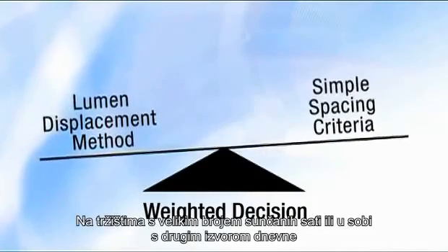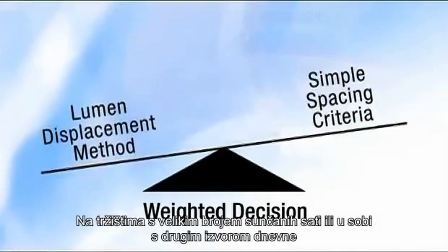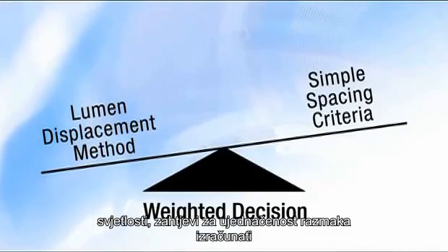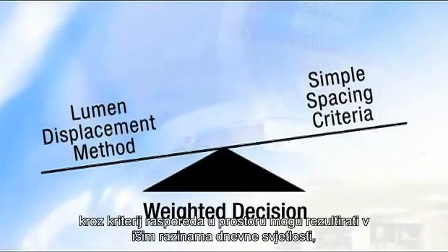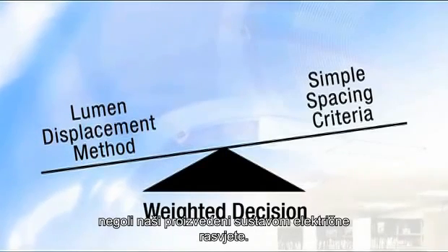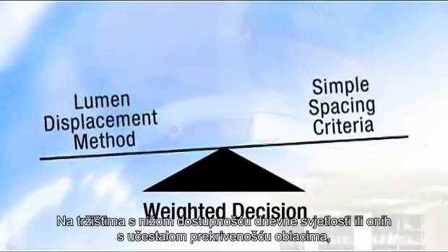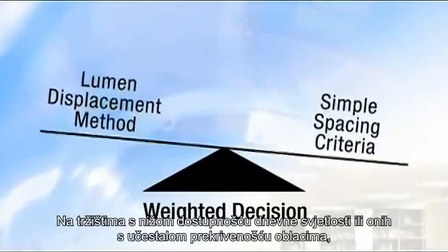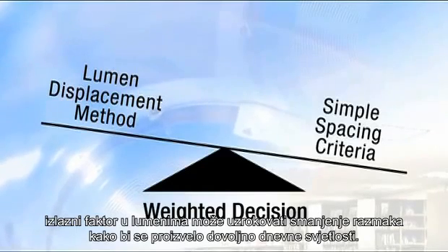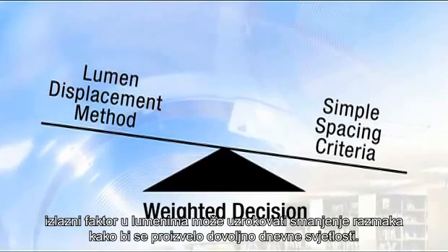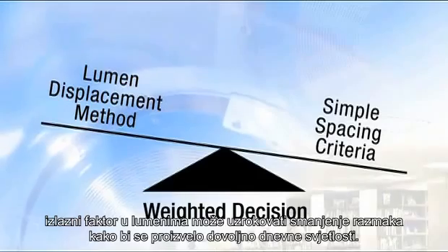In sunny markets, or in a room with other sources of daylight, spacing uniformity requirements calculated through the spacing criteria may result in higher daytime light levels than are produced with the electric lighting system. In markets with lower daylight availability or those with frequent cloud cover, the lumen output factor may cause spacing to decrease in order to provide sufficient daytime light.